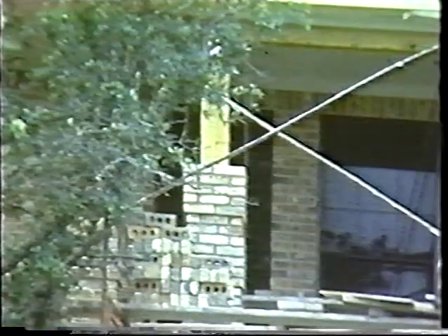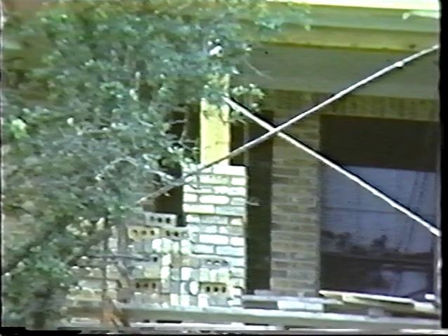Arches often abut or sit on columns as an architectural feature. But unless the brick veneer which surrounds the wood column is braced, it may not be strong enough to resist the thrust from the arch. The abutments rotate, giving rise to cracks and a possible failure. Other means of abutment support, such as a roof or window frame, are usually not adequate.